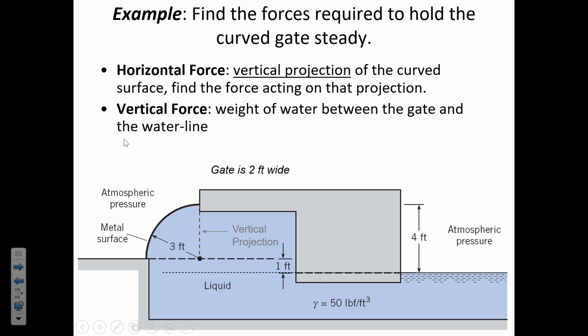So we've got to ask ourselves, what's the relationship between the water line and the centroid? So, like, what's that distance? Remember, hydrostatic force is the pressure at the centroid times the area, which is delta H times gamma times the area. Okay, so the gamma here, it says it's water. So unit weight is 9810 newtons per meter cubed. Area we've defined by the vertical projection. I don't want to say too much more.